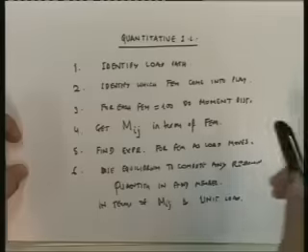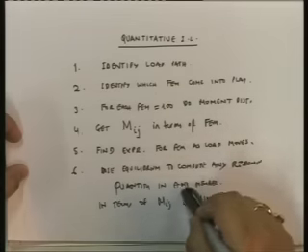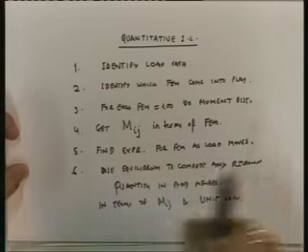For a statically indeterminate structure, we can still continue using the Müller-Breslau principle, but it only gives us a qualitative sense of the influence line. To get a quantitative sense, you have to go through the direct approach, in which you make each member statically determinate and then solve for it. So much for influence lines.